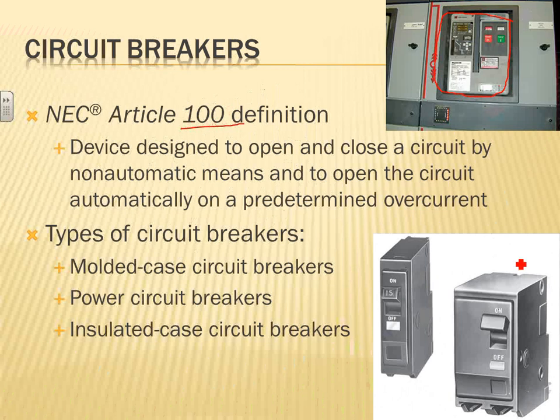And then for the rest of them, a lot of us will use molded case circuit breakers. I believe molded case circuit breakers can go up to 1,200 amp. Anybody correct me if I'm wrong here. At voltages of 600 volt, 480, 250 and so forth, 1,200 amp. And then after that 1,200 amp, if you need 6,000 amp, which is rarely used, then you have to go to where? 6,000 amp, you have to go to power circuit breakers.